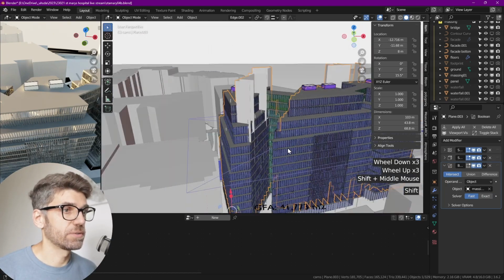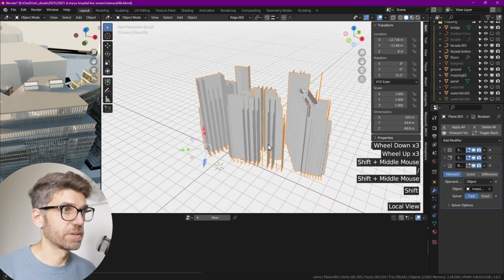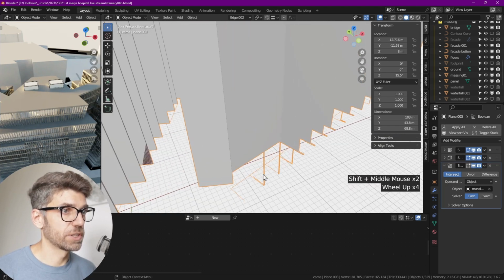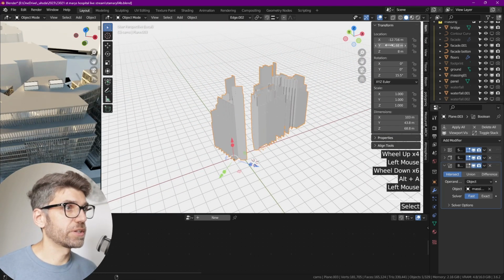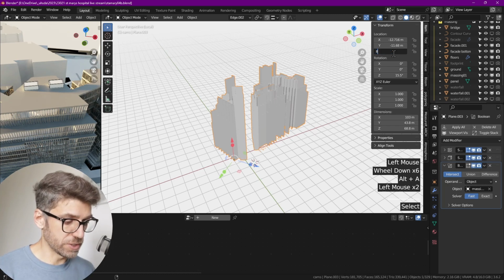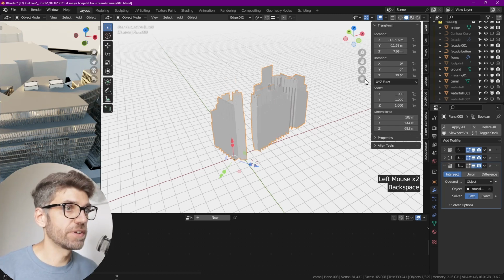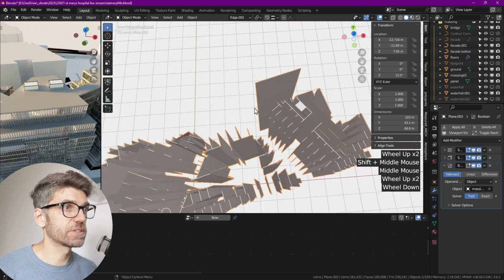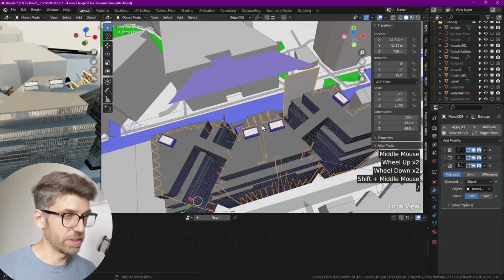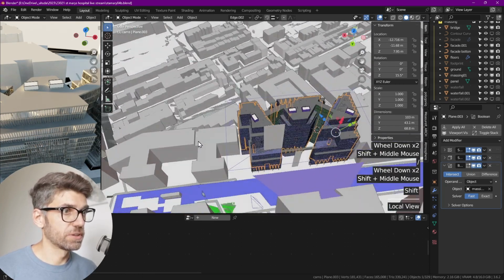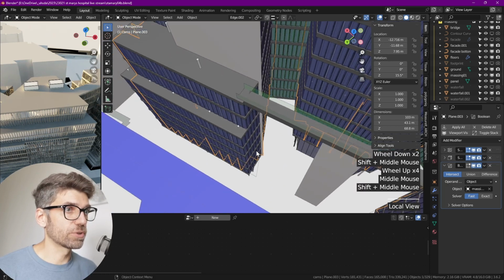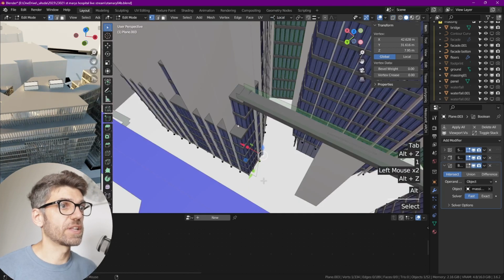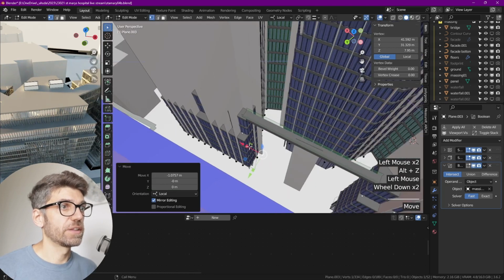Fast. Yeah, so that boolean is not terribly happy here. Oh, it worked. For the most part. There's some challenges, like at the bottom. So sometimes what I do is have something like 7.95, just so things snap a little bit better. And you see that improved most of the things, except that odd wall that we have in there. Let's see what's going on with it. So that must be getting too close to an edge also. So if we try to move that slightly out or slightly in, that sometimes helps.